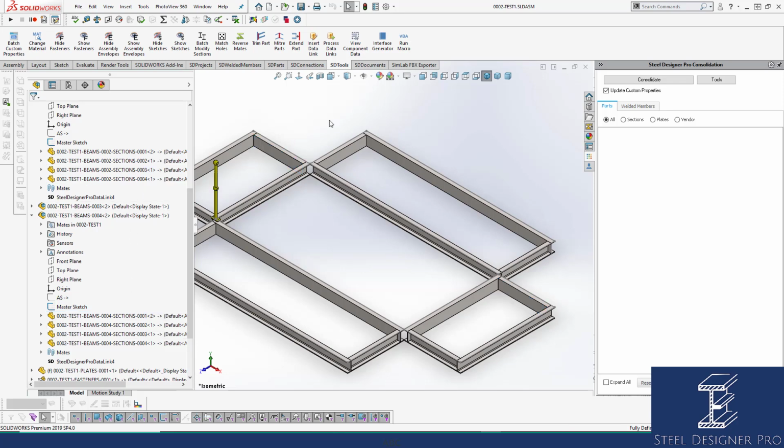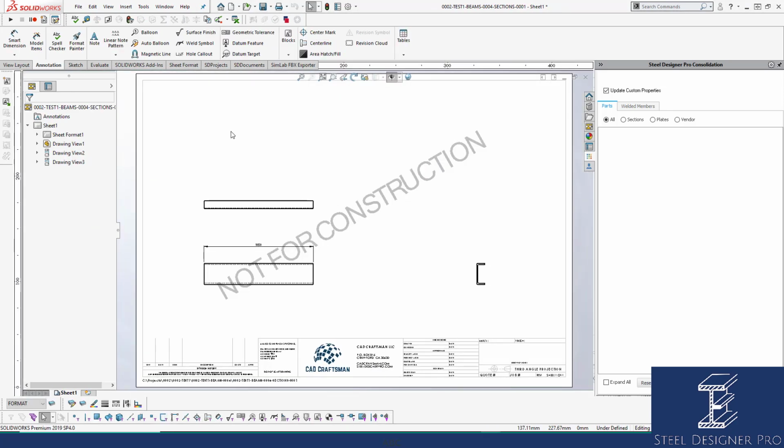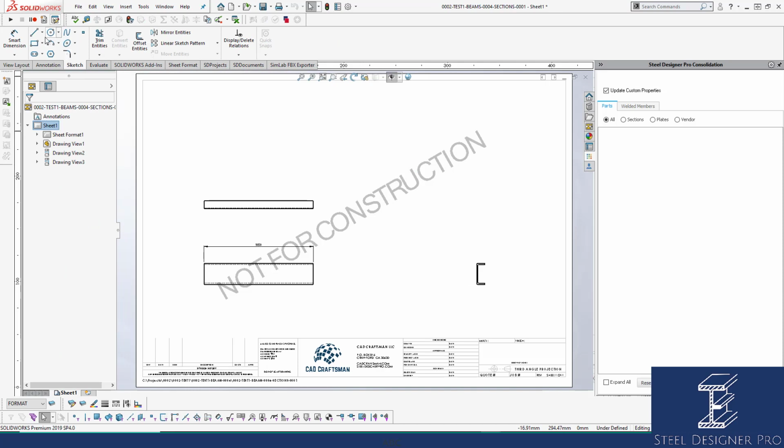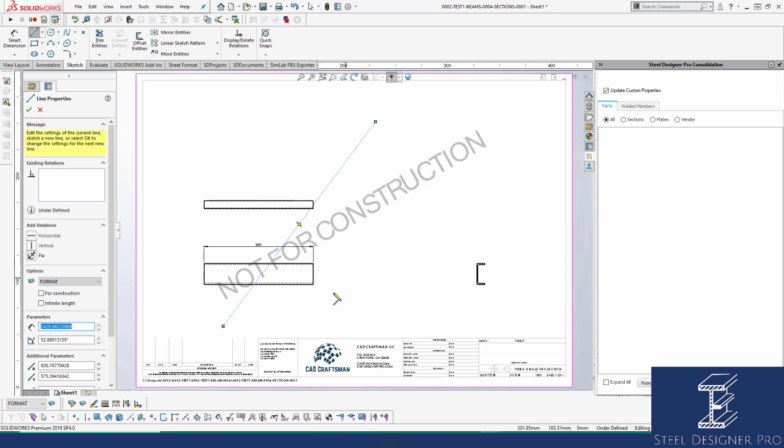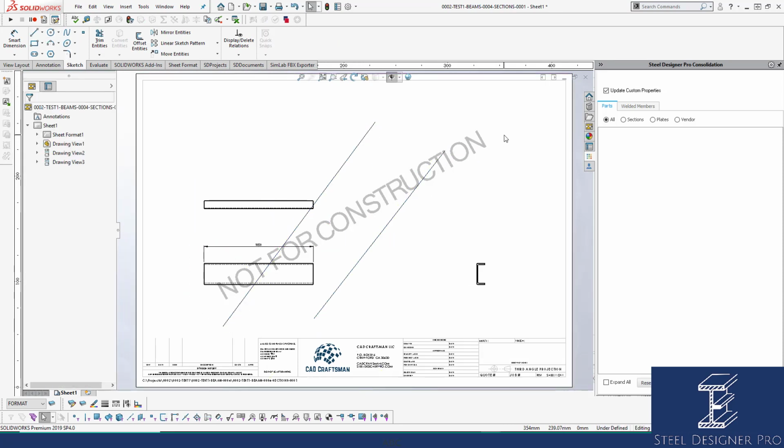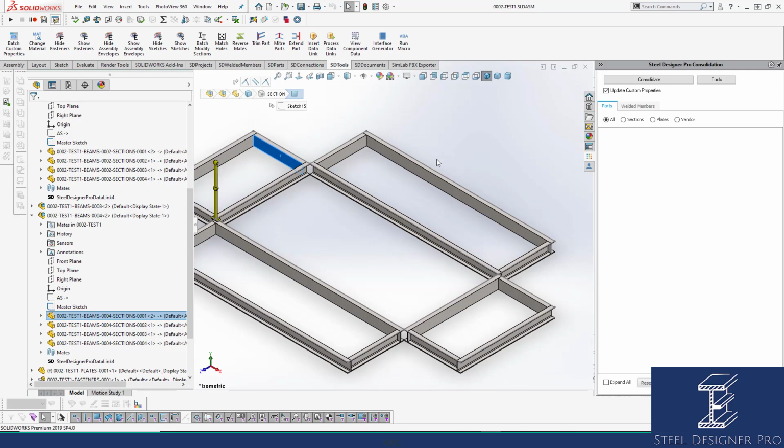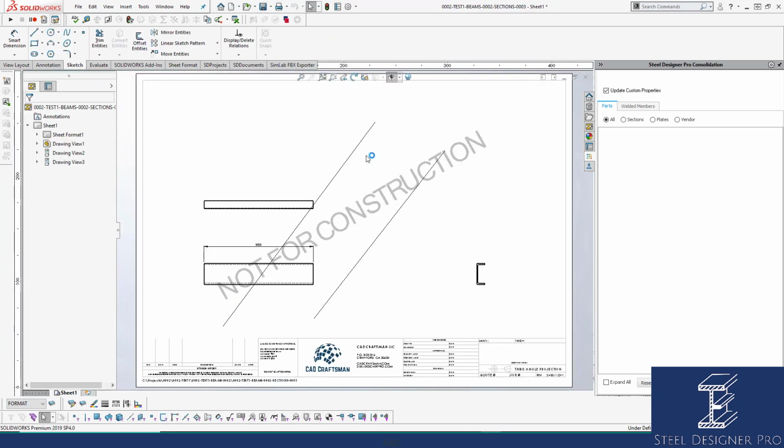But because of the consolidation running in the background, when we go to open up this drawing, and then change this drawing, let's just say we draw 2 lines across it and then hit save, close the drawing off, and then go over to the other one and open up its drawing, you'll notice that because of consolidation, it's automatically updated the drawing when we click save on the drawing we've made changes to.